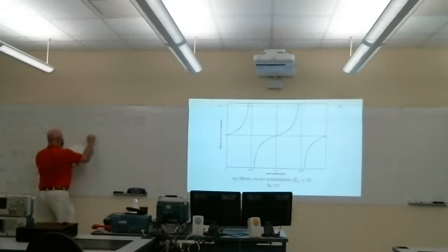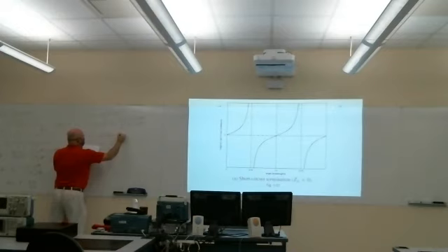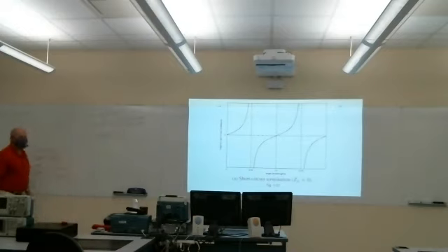Now, often we try to match the load to the line so that we don't get this standing wave set up, and our input impedance is equal to Z0.